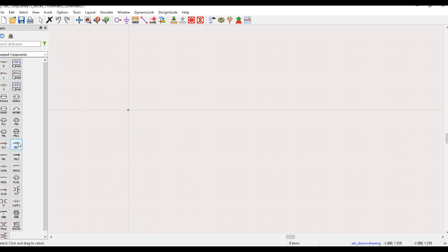So we now go to the parameters tab and select what we want to display. So here we ensure that S parameter is selected because that's what we want to show, and then we click on OK. So our design is now set for simulation. On the menu, we now click on the run simulation, which is this sign. Clicking this will now run our simulation. That's the simulation icon from the toolbar.